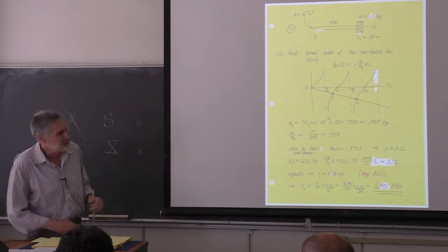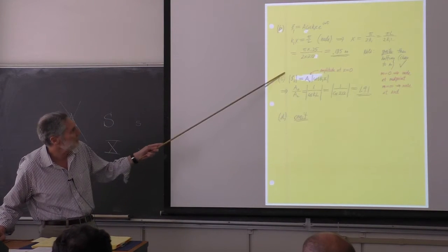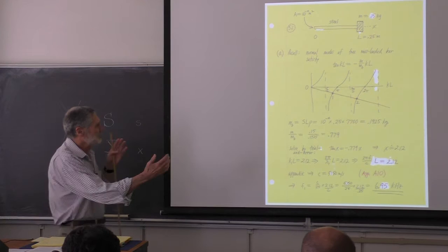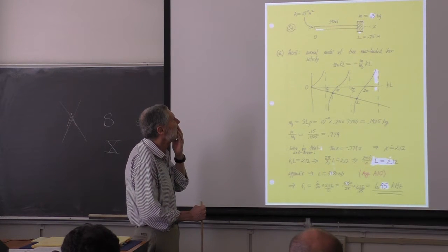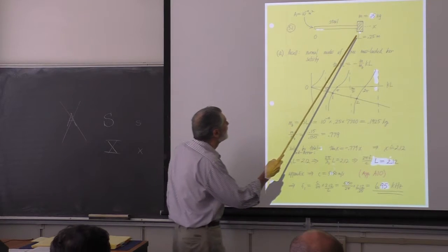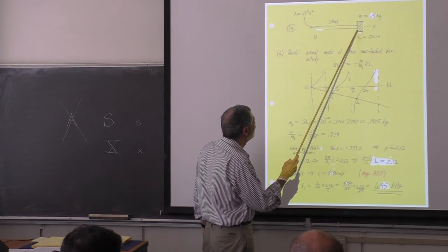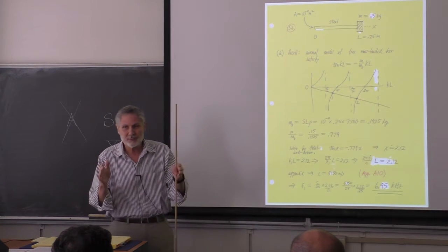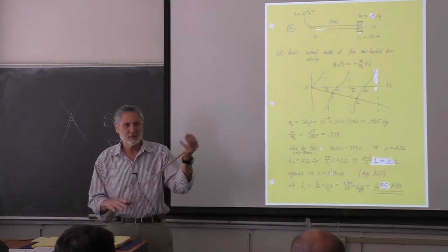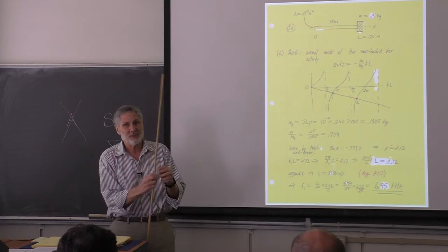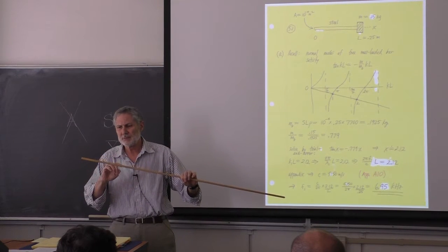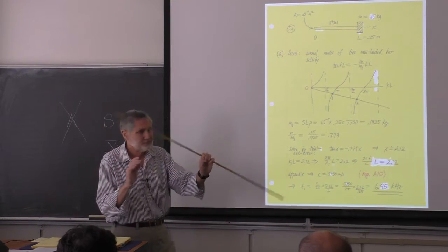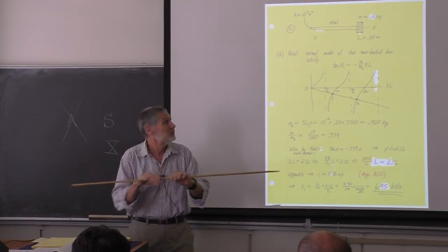Okay, I jumped right into this in the solution here, but we need to look a little bit more physically. I put it over here. So this is going to have a fundamental mode. What does that look like? Well, if we're a fixed end, we would have a free bar. And what does the fundamental mode of a free bar look like? There's a node right in the middle. That's the demo, right? Remember the rosin. So there's one interior node, symmetrically located.